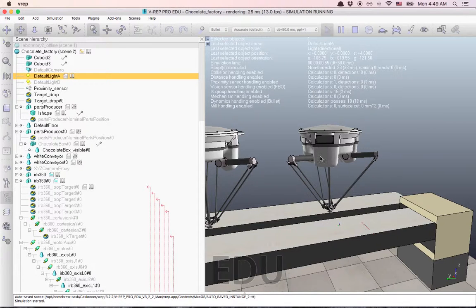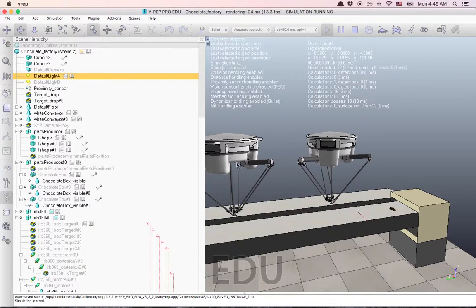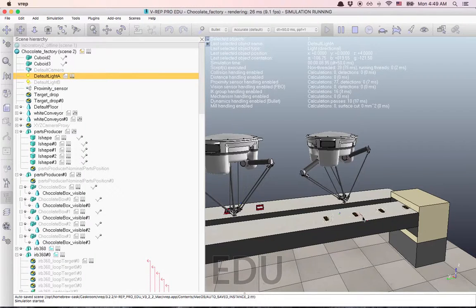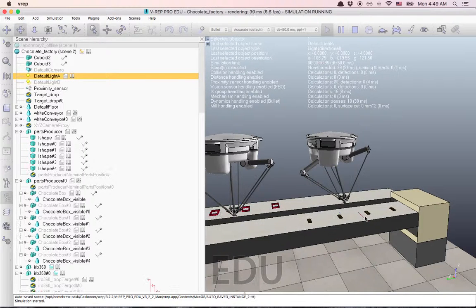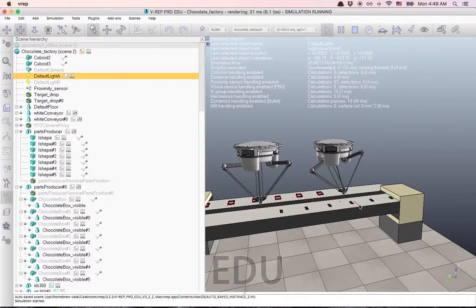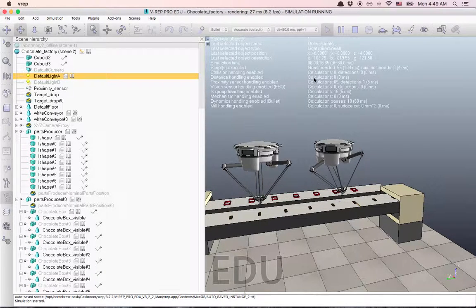This robot will not move because I haven't changed this code, and this code is telling the robot to wait for this one. As you saw, as soon as we detected the chocolate, it moved. It's waiting, and as soon as we detect the chocolate, it moves. So now you know how to do sensor-robot communication and robot-robot communication. This will be all that you need to create the cooperation environment that you need for both of the laboratories.